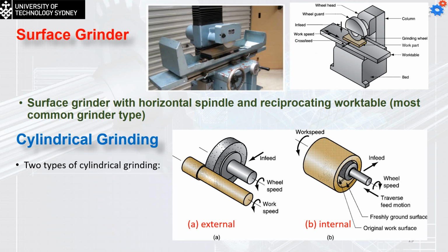Well, one of the suggestions in the sheet you are going to have tells you, okay, now we try to put it in water, and you will find the volume of water that is raised, and this volume will be the volume of the shaft you had. Actually, I can give you a simple way. Now you know the material of this shaft, then you can find its density. I think it's something like 7,300 kilogram per cubic meter or 7,800 kilogram per cubic meter.